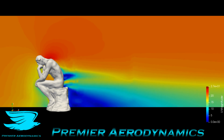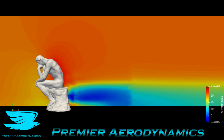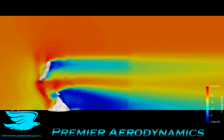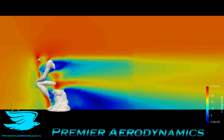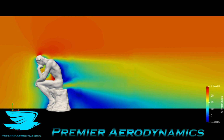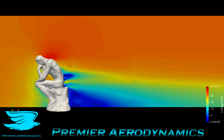And then the fluid going around the shoulders actually accelerates quite a lot because they are fairly rounded, and you can see the back is a little bit rounded, so that means that the fluid is going to stay attached much better and have to accelerate because it's going over a curved surface, and that's called the Coanda effect. And then through the arm, the fluid does accelerate a little bit, as we mentioned earlier in the other streamlines, but then as it gets past the left arm, that little hole there, it then has to expand, and then it decelerates, loses a lot of speed.